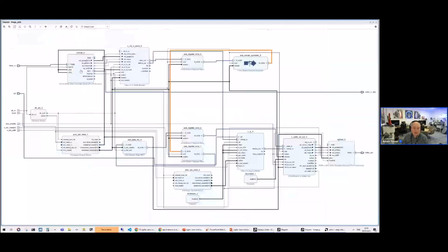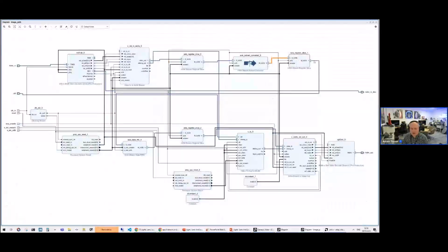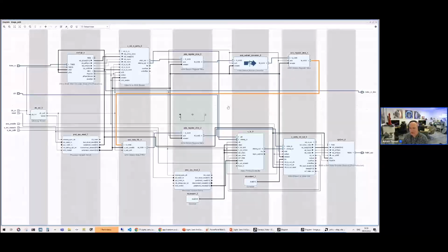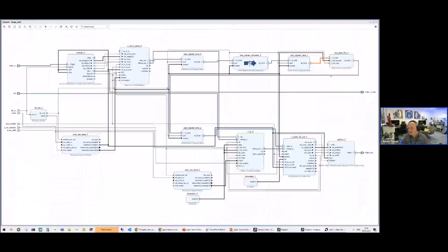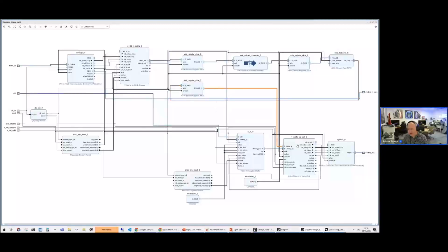Then the output of that subset converter goes through another register slice, just because I'm being paranoid, and then it goes into a small FIFO. This small FIFO is just to make sure that if there's any slowness, any breaks in the parallel image processing stream, it's handled. Then there's another slice, because I think I was getting exceptionally paranoid at this time.